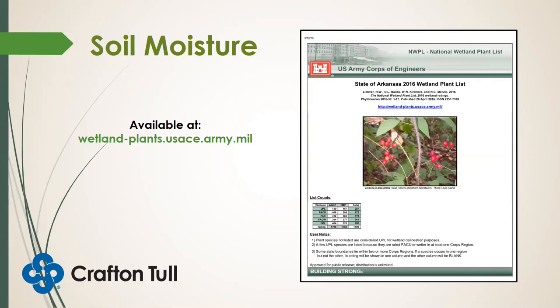And then we'll take whatever seed mix is specified, mix it all in, and you can get much more comprehensive and effective vegetation, and it'll be more consistent, so you don't have to worry about these patchy areas. But it does require that you make sure the area is graded out, you don't have a lot of ruts, because you want to make sure that it's all applied correctly. But yes, it is a very effective method.